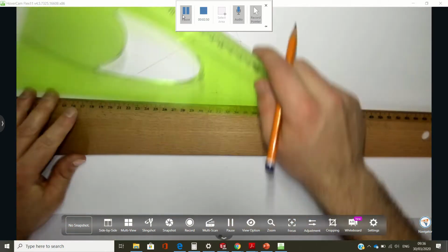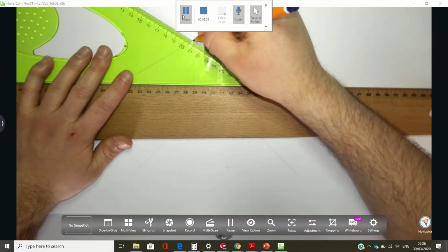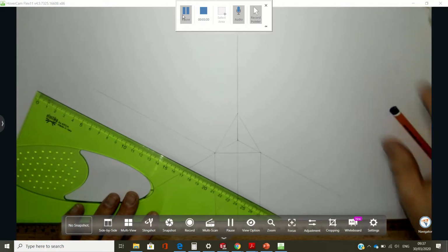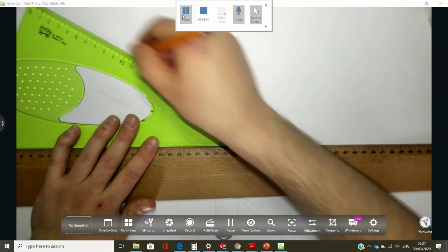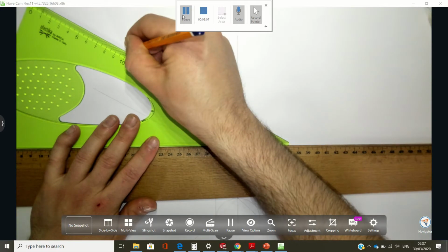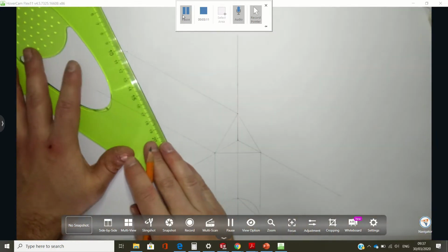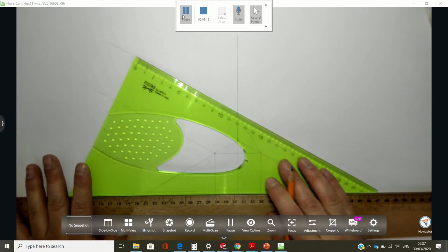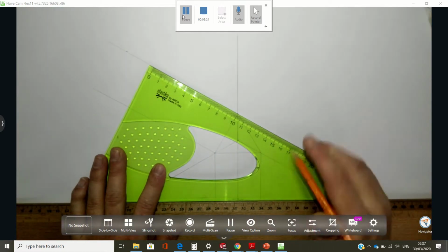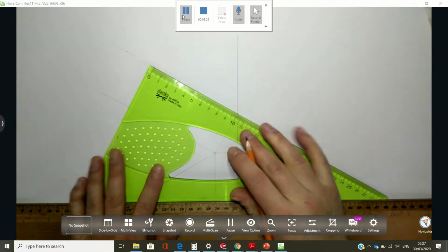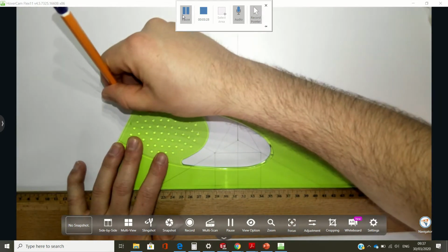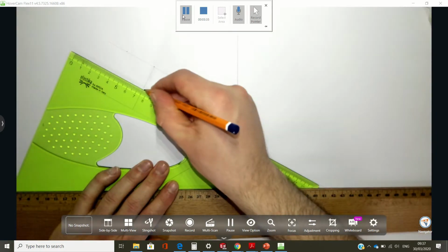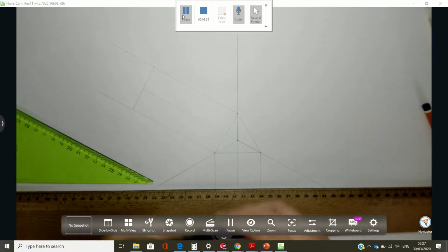Okay, the construction first. So from the corners of the rectangle, I'm going to draw out at 30 degrees, so I'll move the visualizer now. You can go at any distance you want, but I'm going to recommend possibly 130. Okay, no, I won't recommend 130, as I wouldn't have enough room then to finish it, because the height of the elevation would be 160. So I'm going to go back 100. Okay, 60 degree line, so it's parallel to the edge of the equilateral triangle. Extend on your axis there for your center point, and then we're going to draw in the semicircle.